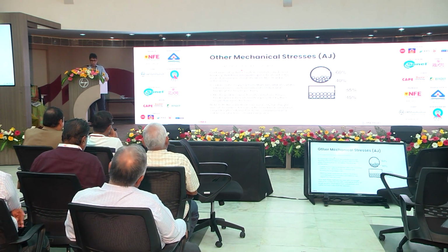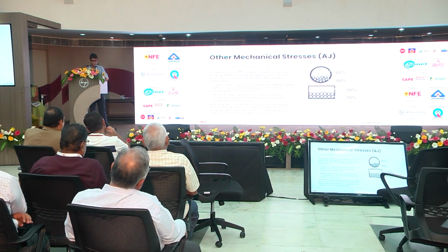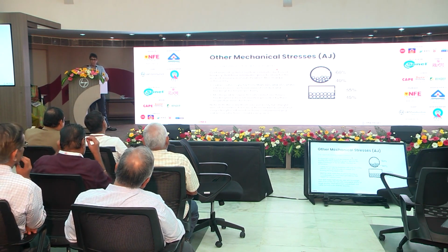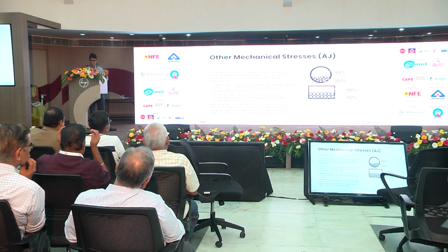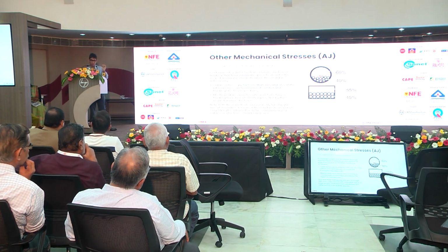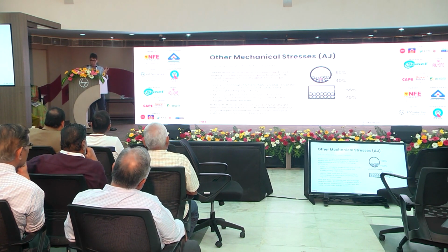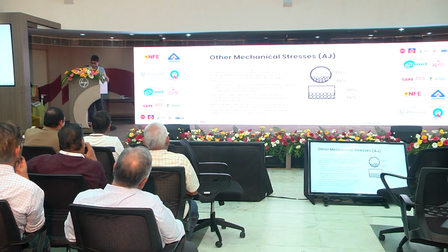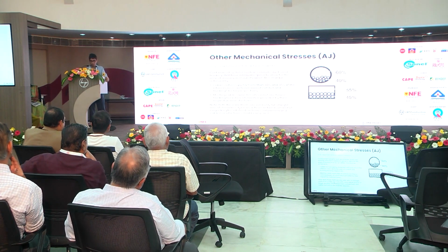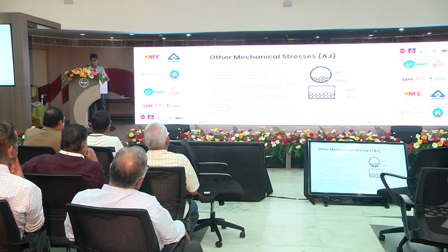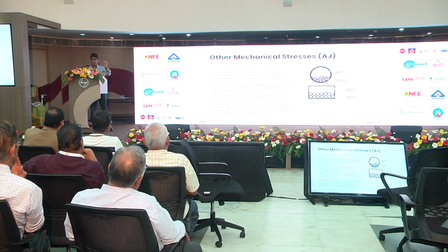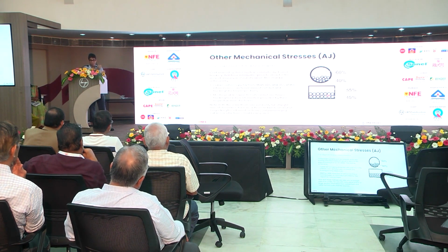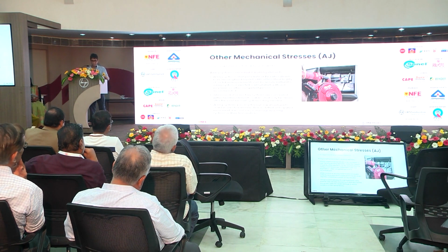There is further guidance on this in section 9, part 1 of SP 30, clause 5.4.9, which allows slightly greater percentages, you can fill the conduit and ducting to slightly greater percentages depending on the type of cable. Please refer to that. By the way, these are only valid for straight runs of less than 3 meters with no bend. The moment you introduce a bend, from a pulling point of view, you are introducing further mechanical stresses. So then you need to look at the manufacturer information. They will usually provide this.